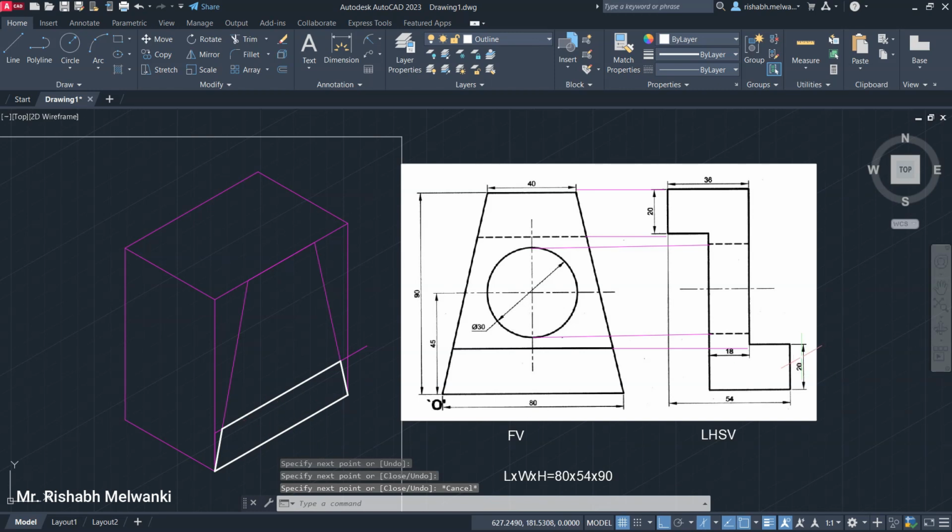Now next, if you observe, the total width is 54, this much is 36. So 36, 54 minus 36 will be 18. So basically this part is 18, this part is 18, and last part is also 18. So from here we will have a step. Okay, so we have to move in backward direction. How we can understand that?